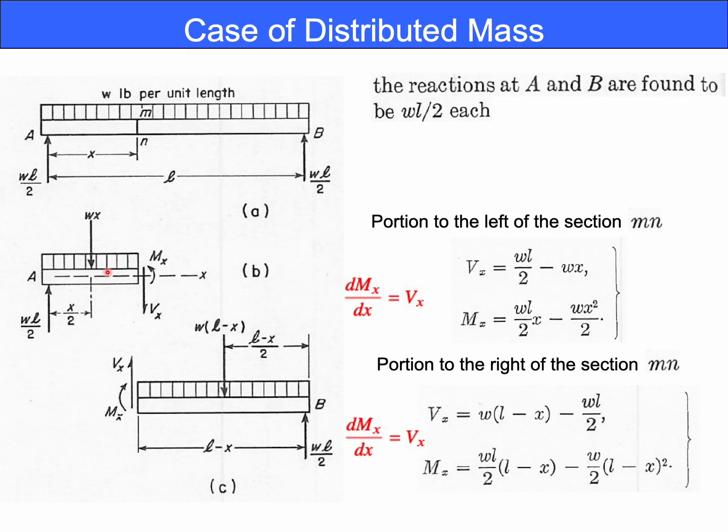So for this case, you still have the distributed load like this, but it is equivalent to have the concentrated load at the center. So its value is Wx. Okay, integrating W from 0 to X, you obtain this as the concentrated load, the equivalent load.